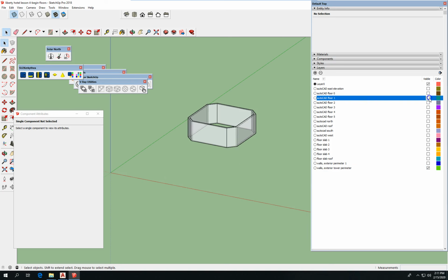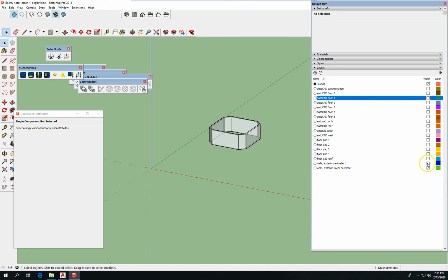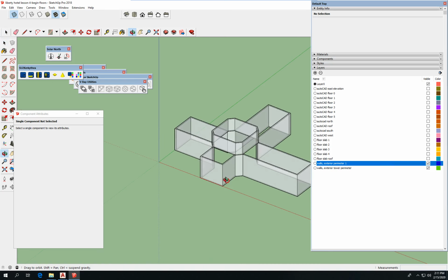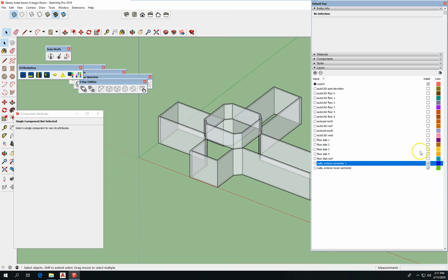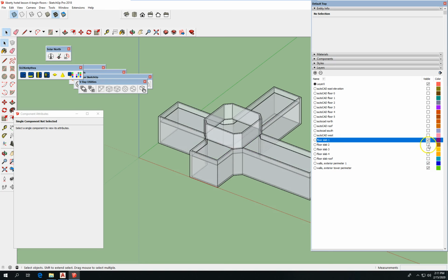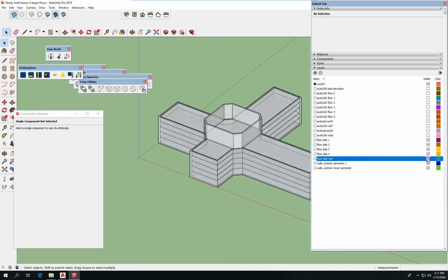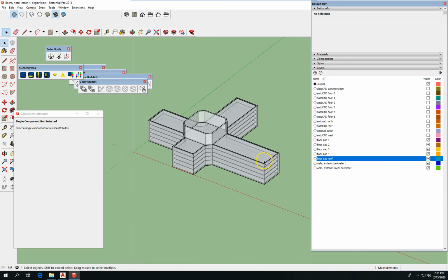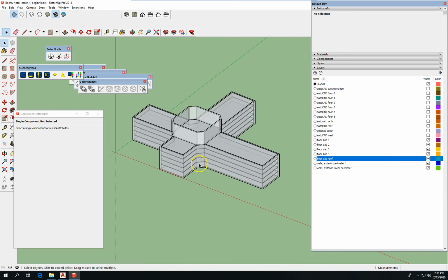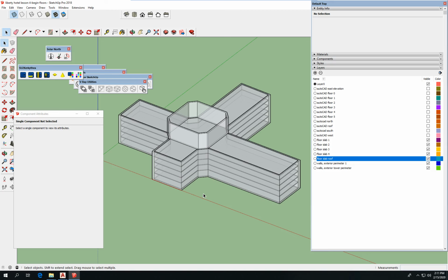If I turn off AutoCAD and now just turn on the geometry that I'm modeling, you see how that works? And the floor slabs, 1, 2, 3, 5. Now all that's left to model is the shape of the roof itself. So I'm going to save out that lesson, this 15-minute lesson, begin floors and tower.